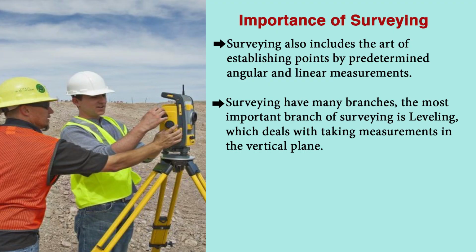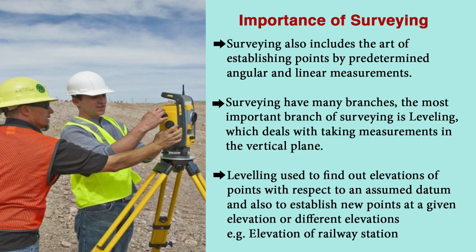Surveying has many branches. The most important branch of surveying is leveling, which deals with taking measurements in the vertical plane. In the vertical plane, the most important measurement is the elevation of the points. Elevation I have explained earlier. So leveling is used to find out the elevation of a point with respect to an assumed datum and also to establish new points at a given elevation or given different elevations.